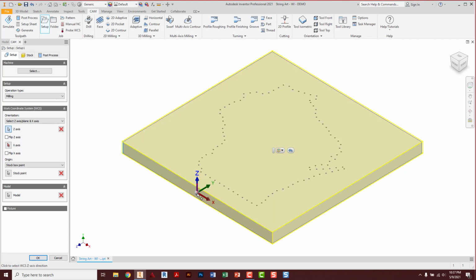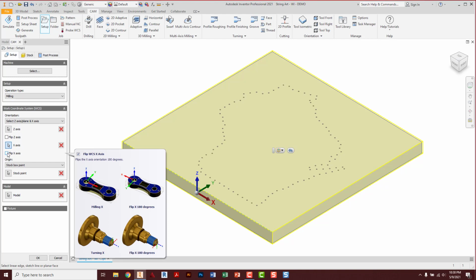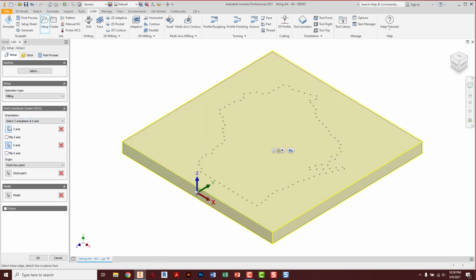Now this datum, or this little ball joint there connecting the XYZ, it's not quite in the right spot yet, but at least it's pointing the right direction. And if yours isn't going the right direction, you may also have to click X, which I thought I would do, and I would have used this edge to be X, which is not going to do anything, but you can also check these boxes to flip them if you're still not getting what you want. So it's a combination of picking edges, maybe flipping the axes to eventually get the XYZ in this orientation.